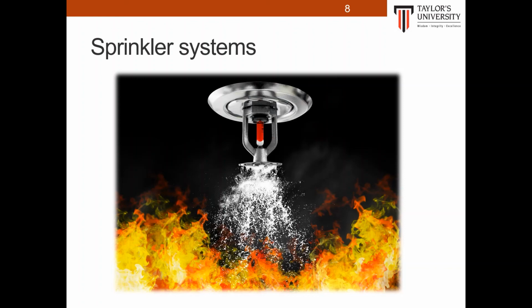The common approach activates the heads individually by the melting of a fusible link holding a plug in the head assembly. Once activated, the sprinkler cannot be turned off unless the main water supply is stopped. This approach is what we call a wet pipe system. These systems are normally used for storage areas, laboratories, control rooms, and small pilot areas.